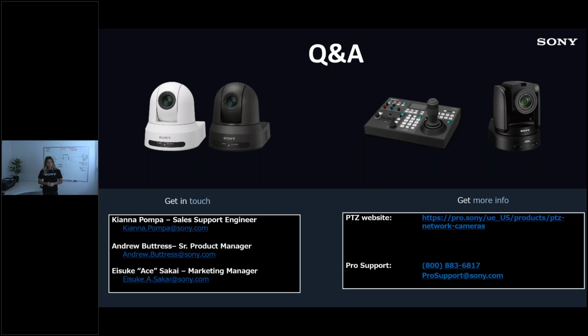Your eye can't necessarily detect that kind of latency, but again, in a lot of IMAG applications, you're going to run into a video switcher that's adding in some frame buffering. Then you're going to run that program out to a projector or a large flat panel display, depending on the application. That's also adding in latency. So by the time you go from the lens to that display, it's more than just the 50 milliseconds because everything else along that video chain is adding in latency.